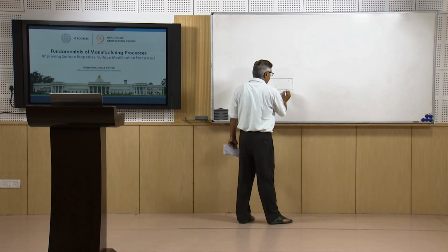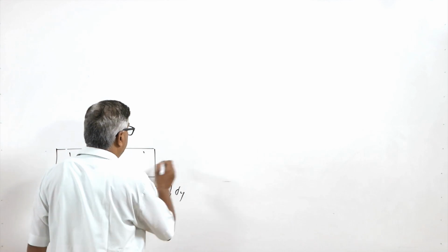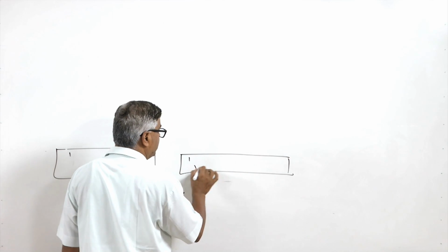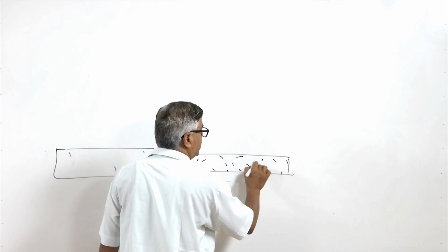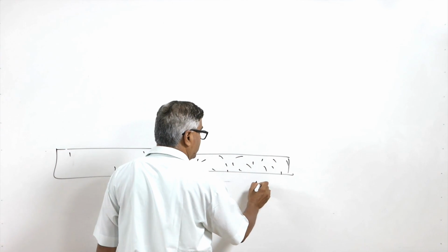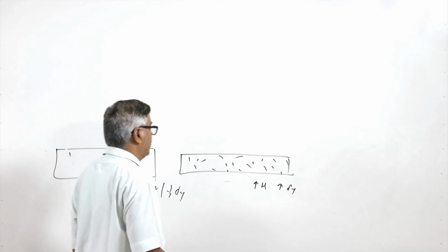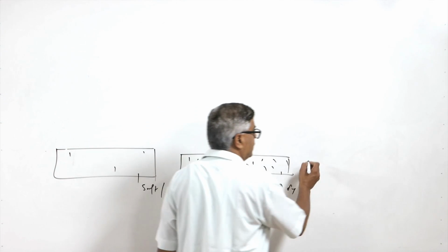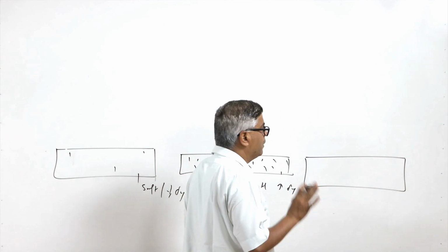dislocations, it will be softer, with a lower yield strength. But if it is subjected to severe plastic deformation, it will lead to the development of a large number of dislocations here and there, and that in turn will lead to increased hardness, increased yield strength, and improved mechanical properties. So, this concept is exploited in surface modification also, wherein there are two approaches.